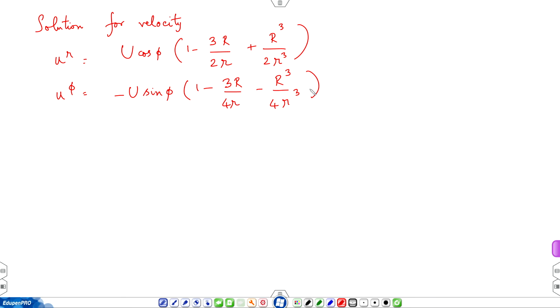Uniform flow would be u equal to capital U in the flow direction here. Similarly for pressure, as you go away from the surface of the sphere, pressure will become the far field pressure, the undisturbed stream pressure, P infinity in the previous slide.